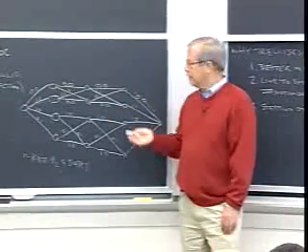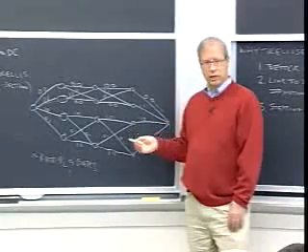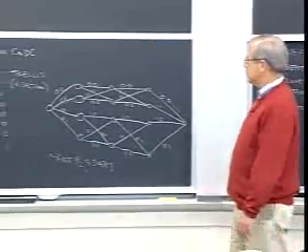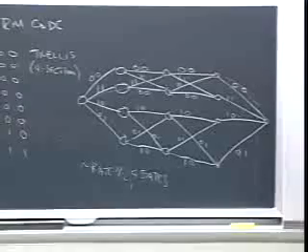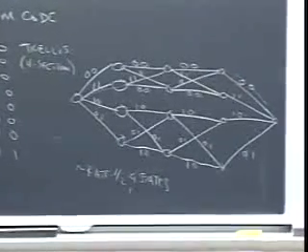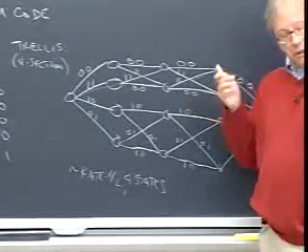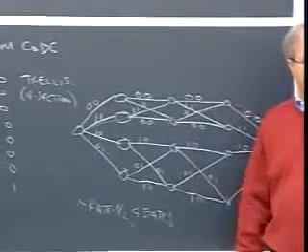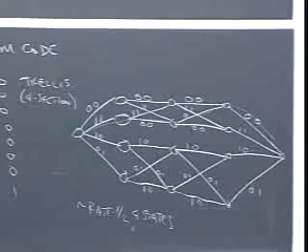And when I said that, this is what I had in mind, that I could decode each of them with a Viterbi algorithm with approximately the same amount of complexity. All right? And unfortunately, this only has a nominal coding gain of 3 dB and an effective coding gain of slightly less than that. So it's not quite as good as the convolutional code. And at the end of the day, we're going to find out that that's kind of typical of comparison between block and convolutional codes of the same trellis complexity.